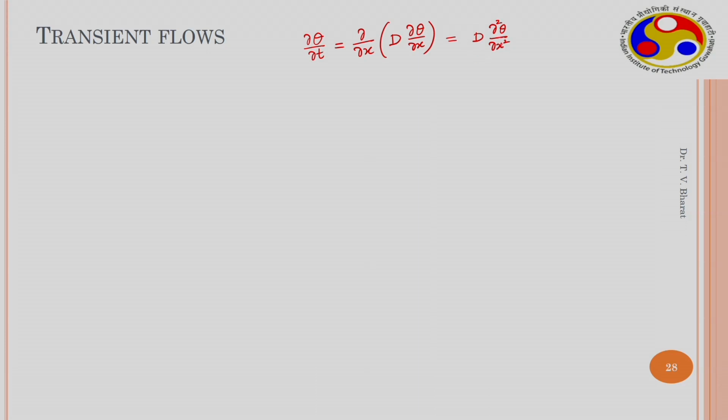So this we applied in case of a small sample which is tested in axis translation technique or pressure plate apparatus using the method of multi-step outflow technique for the estimation of hydraulic conductivity function. So in that we made a similar approximation, however the representation was in the head form, or the suction was used as a dependent variable.